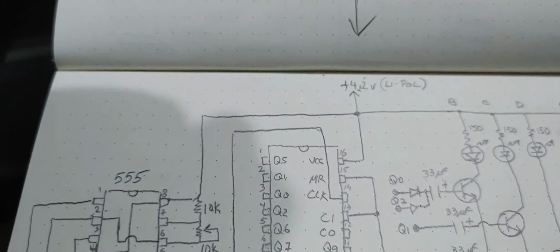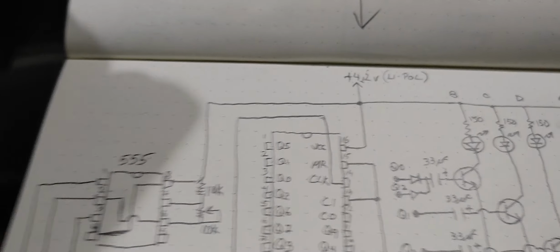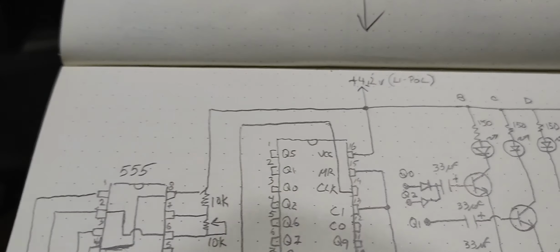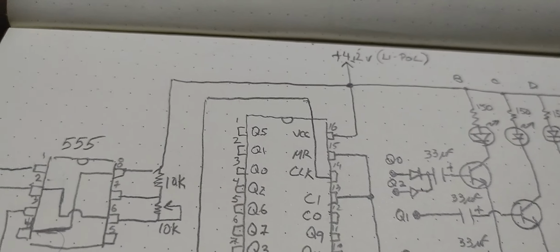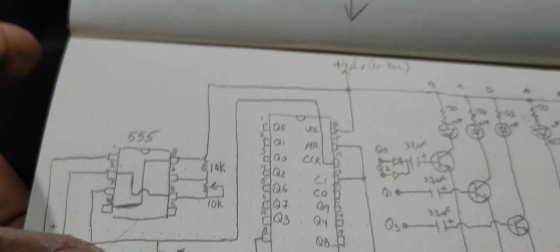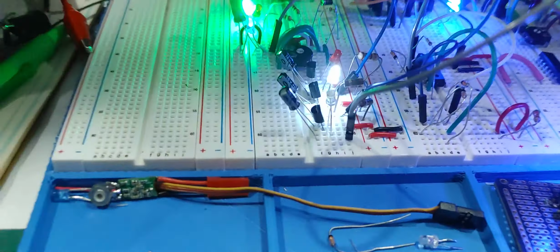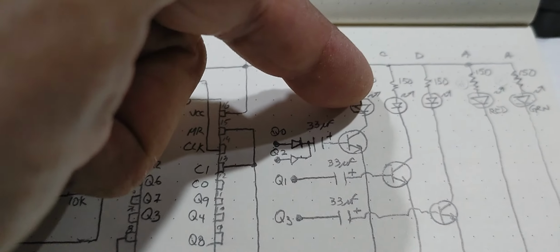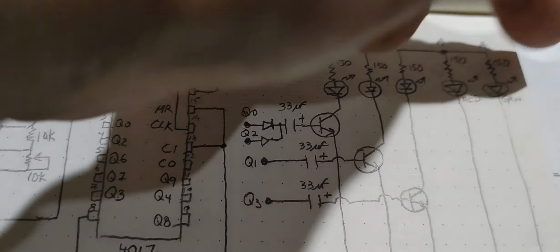But all that can be figured out by the specifications of the particular LEDs, because not all color LEDs have the same specifications. Some consume a little more current, some consume less current, and they require different resistors. But for this application, I experimented with all that, and for simplicity, I just decided to keep all the resistors the same here. So I'm using 150 for all these resistors, including the ones that are connected directly to V plus and ground, which are the ones that remain on, the green and red LED on the wing.